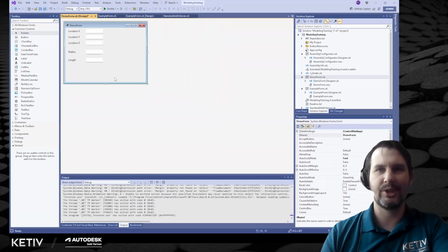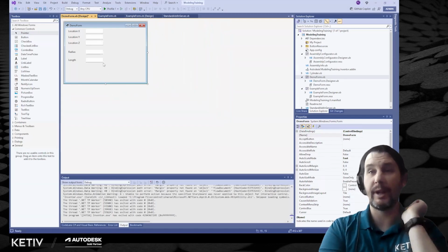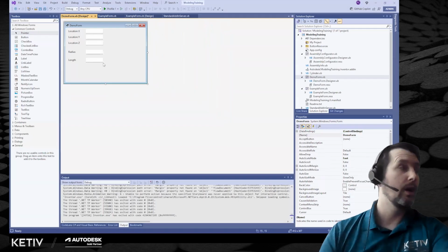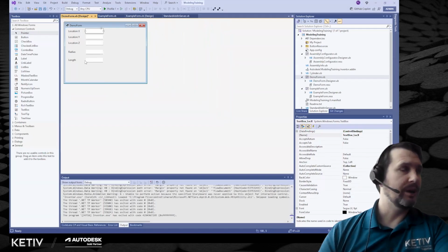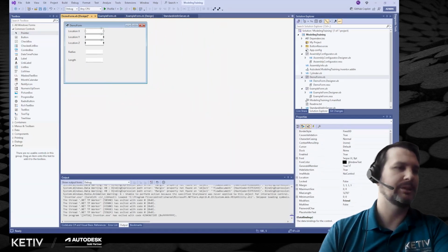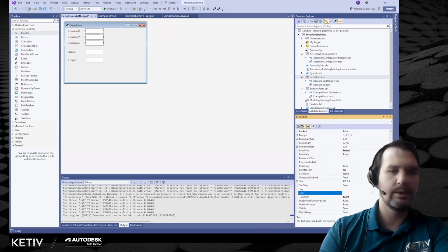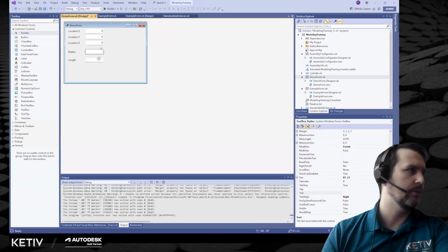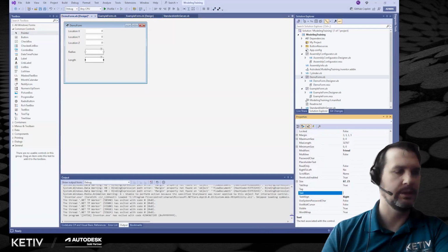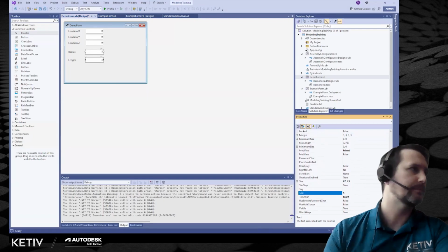So if you hit go, your add-in isn't failing. So for these, most of those default values, 0 would be fine. 0 radius and length don't make much sense and would fail. So let's go down to the text value, put in 0 for these three. And for radius and length, I'm just going to put in a non-zero number. So we'll say 5.